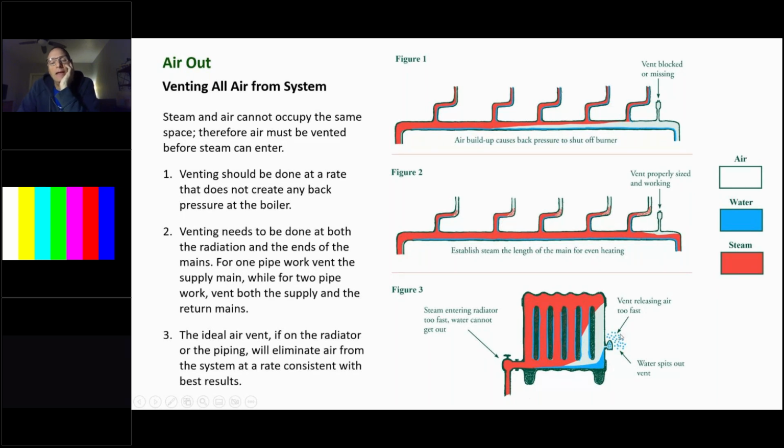So again, going back to those, if you go through a house and you see that say it's got 10 radiators and 4 of them have the number 40 Hoffman vent, which is a non-adjustable vent, and then the other 6 radiators have the 1A adjustable air vent, then we're not getting a balanced flow through the radiators.